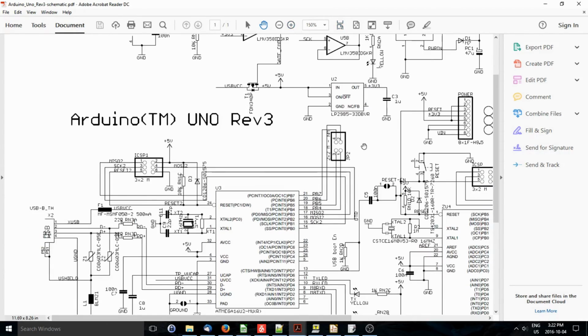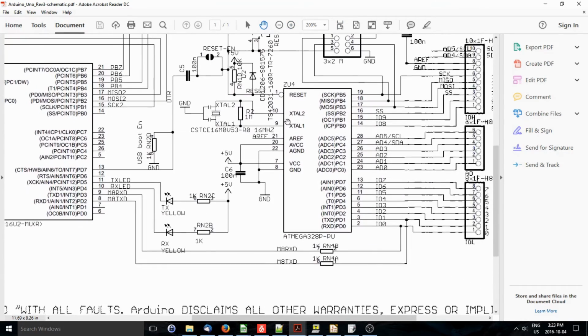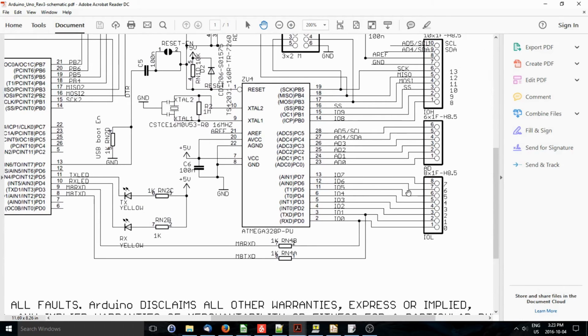Let's zoom in here so we can see what we're doing. PD6 is Arduino pin 6. So that's what we need to look at. This is so I can figure out which connector I want to connect to. So it's pin 6. Alright. Back to the code.